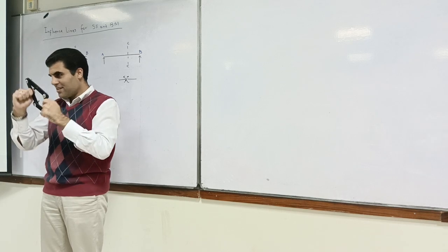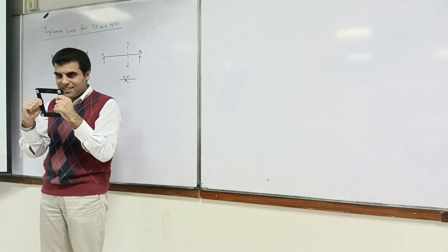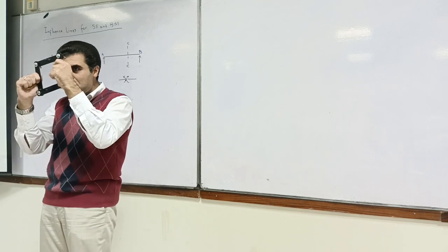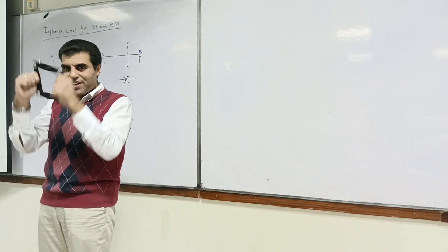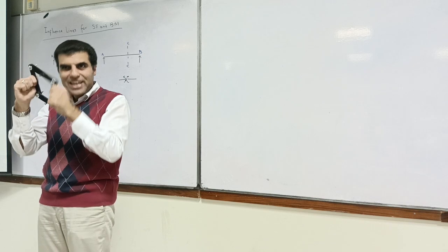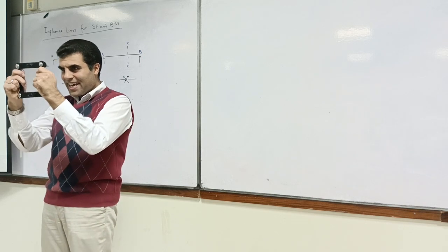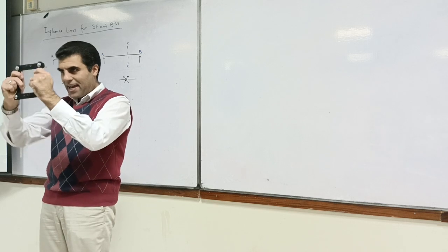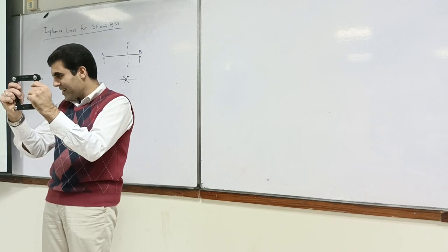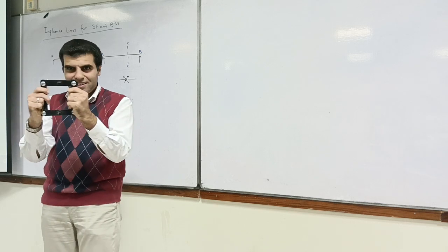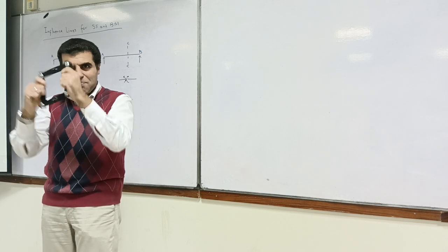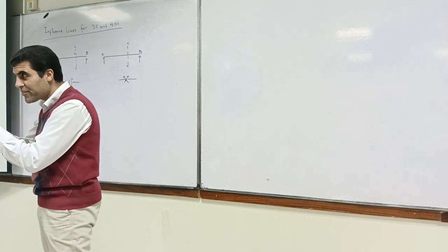No. It can't take any shear, can it? So that means that if we provide something like this, that will actually release our shear, isn't it? Yes. Now this thing can take moment. I can apply moment, can't I? But I can't apply any shear. Do you understand my point, sir? Yes.